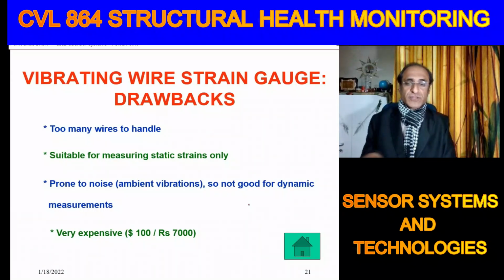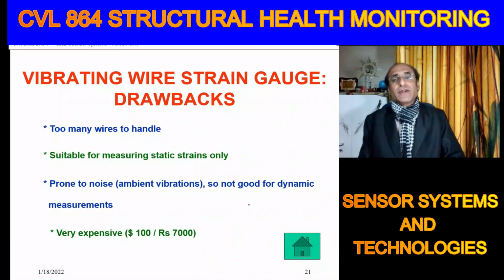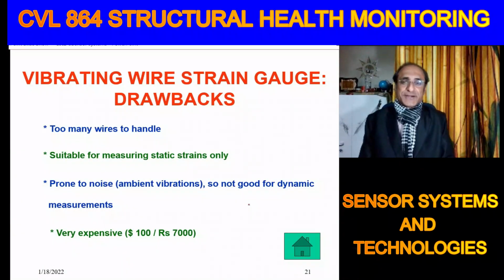Similarly, in a multi-story building, if we install multiple gauges at the bottom where the column makes a junction with the foundation, then as the construction goes on we'll be able to pinpoint the events. For example, when the first floor slab is cast, it will show a change. The second floor, each floor will show a noticeable change. That way, each and every construction event can be very easily monitored by these strain gauges. The other point is the quality of construction. That part, these sensors don't have the jurisdiction over, so the prevalent procedures have to be used.